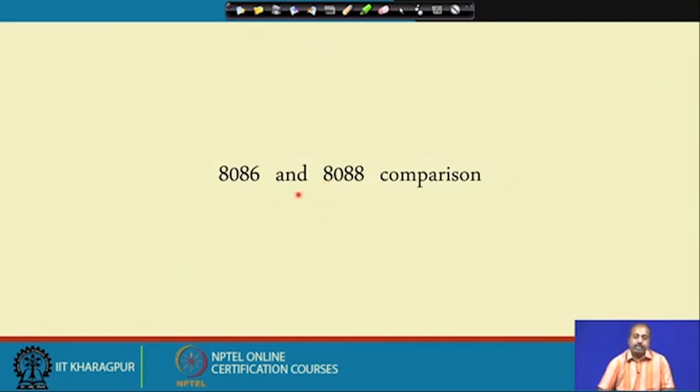So, another interesting thing that has happened with 8086 is when it came to the market. Previously there was 8085. The 8085 interface has a 16-bit address data bus. This data bus was also multiplexed, so altogether it was a 16-bit interface. On a PCB, the processor was occupying some pin locations, and the bus was only 16 bit. But now, if you take out that 8085 chip and put the 8086 chip, it becomes incompatible hardware-wise,